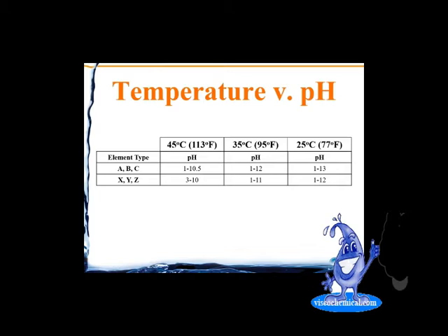But you need to be sure that you have the information from your membrane manufacturer about temperature versus pH. Do not use specification sheets for this.